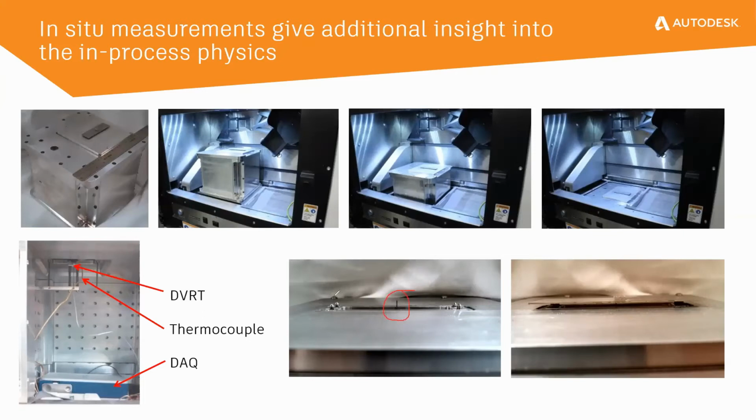This is basically what is over here. You see that we have modified the build plate, and we have a new plate which resides on top of the box, which has a hole through which you get some sensors. And on top of that, we have a new thin build plate that we made, which is this really thin piece of aluminum that you see. And on top of that, we are printing a very, very small geometry that you see over there.